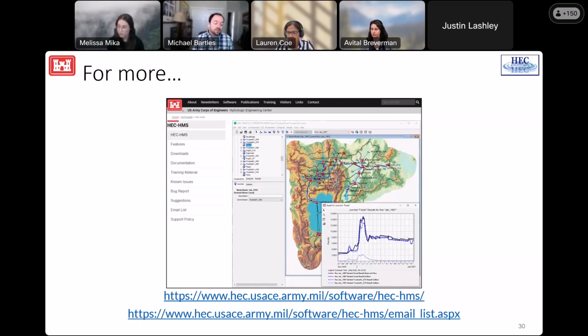The really, really nice thing is that you can narrow the time window to something different than the simulation that you actually compute within HMS or within RAS or whatever else. And you can also change the time step over which you would like to compute statistics. 2 very, very nice features. All right, we had 2 more questions roll in. Before I move on, I want to clarify, if you are grabbing the calibration aid, you can download an EXE also.